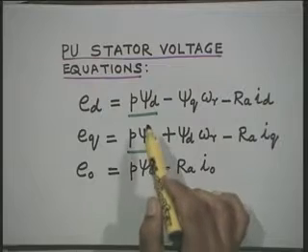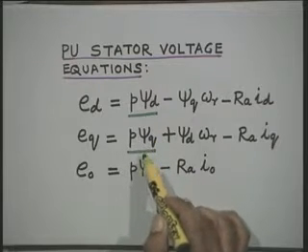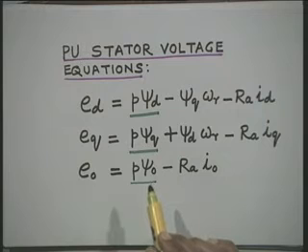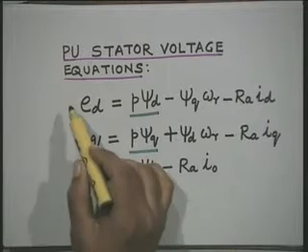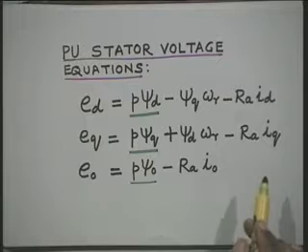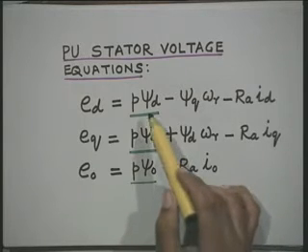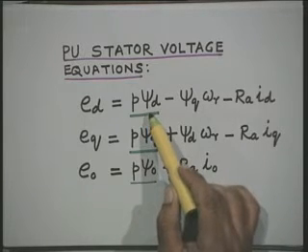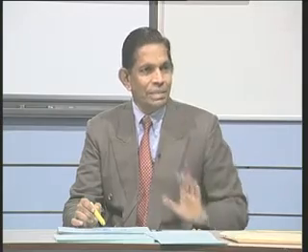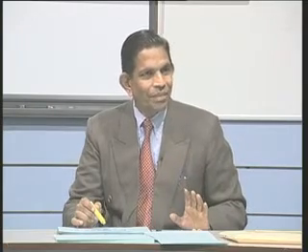And if we neglect the transformer voltage terms, or the derivative terms, then the stator voltage equations become algebraic equations. In fact, these terms represent the stator circuit transients.